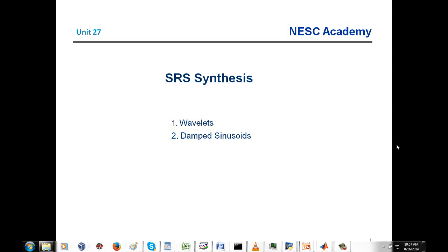So then the customer takes that SRS spec as well as the test article into a test lab for the shock test. Well, the test conductor does not have to reproduce the actual field shock event, which might be impossible to do anyways, given practical limitations, but rather he or she can synthesize a different sort of waveform that will still satisfy the SRS and therefore meet the specification.